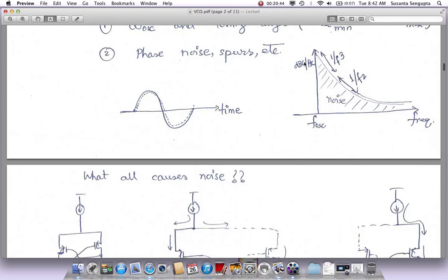So let's say if my carrier is 1 volt, I want to know how low is this noise with respect to this 1 volt, and in dB number. That is what is shown here, but then it is also represented per hertz, because we are not giving the noise itself. Sometimes it's easier to give a density of the noise, because the noise is not going to be, let's say if you're at 2 gigahertz and you said I went 1 megahertz away from 2 gigahertz, you don't have just noise at 1 megahertz. You're also going to have all the frequencies, right?